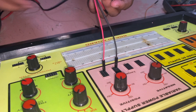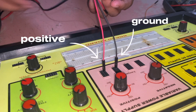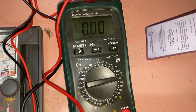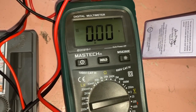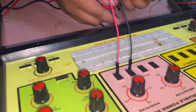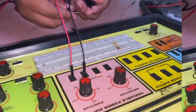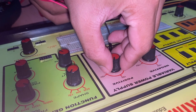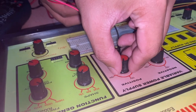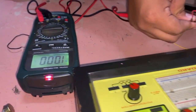Next, we attach the positive and ground wires to the power supply. Using a digital multimeter set to 20 volts DC, we connect the probes to the positive and ground wires. Then, we slowly adjust the positive voltage adjustment knob of the power supply until the meter indicates 10 volts DC.